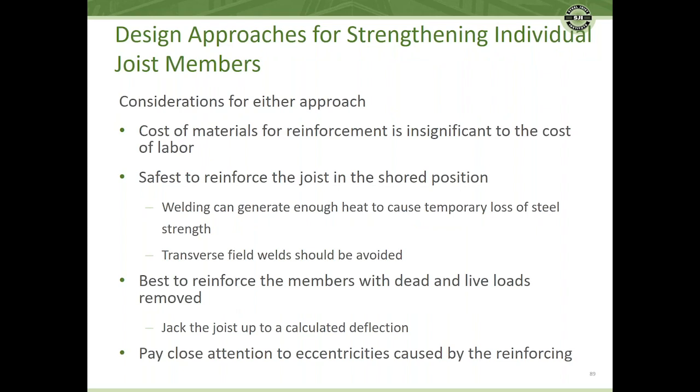One is the cost of materials for reinforcement is generally insignificant compared to the cost of the labor. So being real tight on material really isn't going to help us too much. It's safest to reinforce the joist in a shored position.